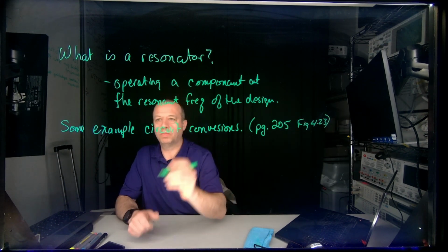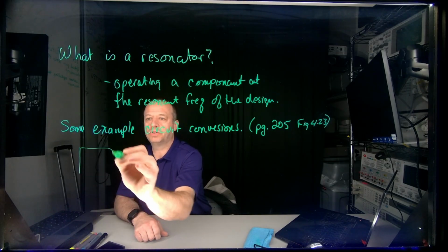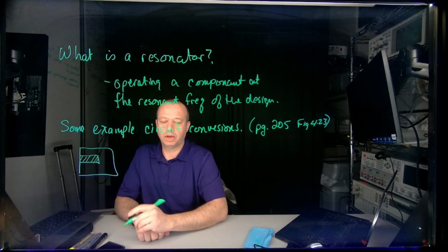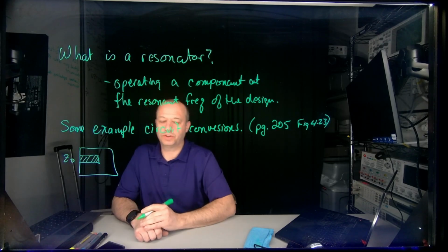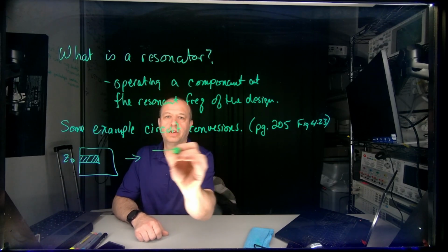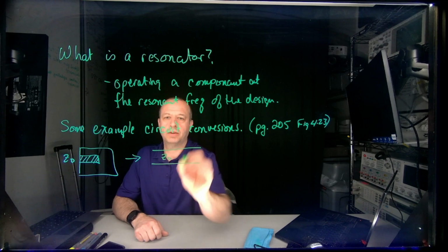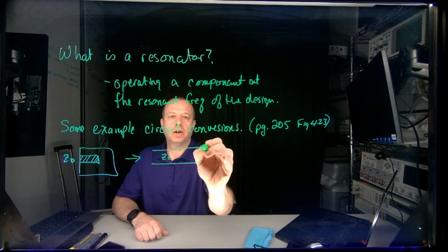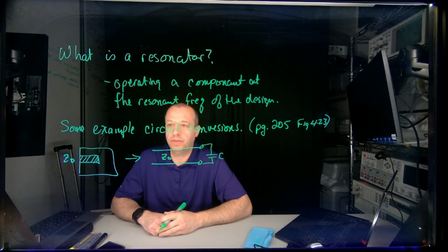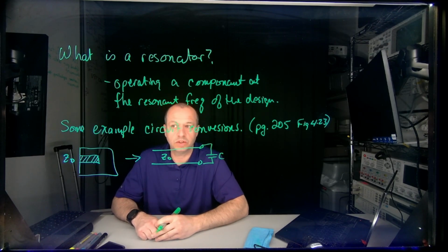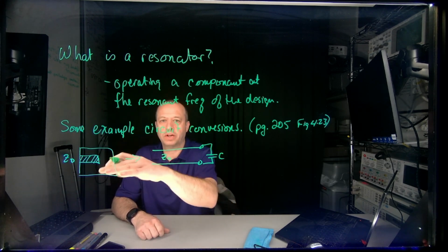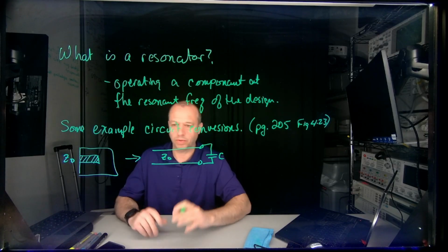When we're talking about, say, a single trace, this being your PCB, and we have a trace coming in at some characteristic impedance, this directly translates into a circuit of a transmission line with some characteristic impedance attached to some capacitor. So that is the direct translation between the two. And so we can take this circuit design and go to trace, or take our trace and build a circuit design. Either way works.